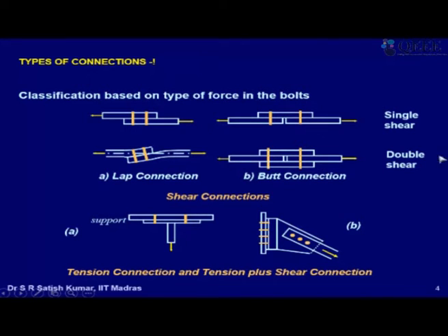So then the bolts are said to be in double shear, and that is just to transmit a single line load. Like our LCD projectors, etc., are hung from the ceiling, right? So what you find is this is called a support or a hanger connection, where something is hung from the ceiling, with bolts put into the ceiling or connected to the beam bottom flange or whatever. In that case, because of this load, the bolts are subjected to tension, right? So the bolts are actually not in shear but in tension. So this is a connection called a tension connection or a hanger connection.